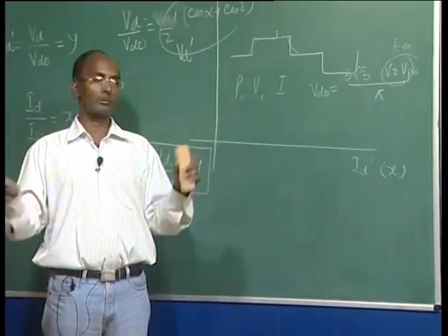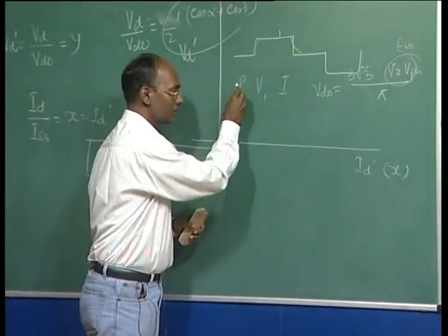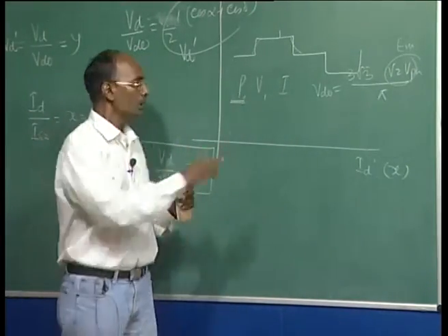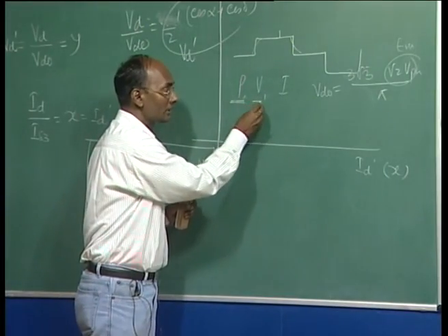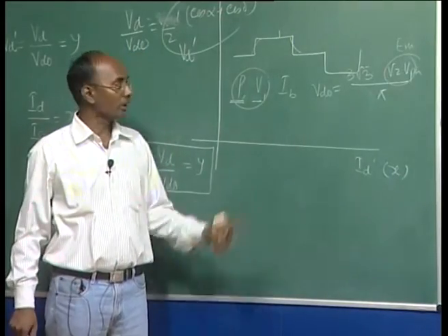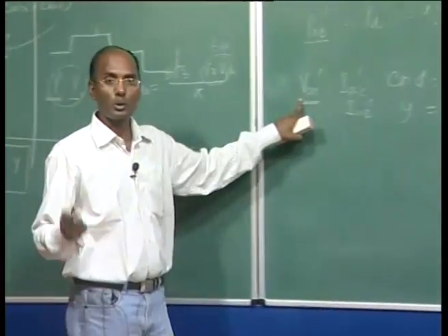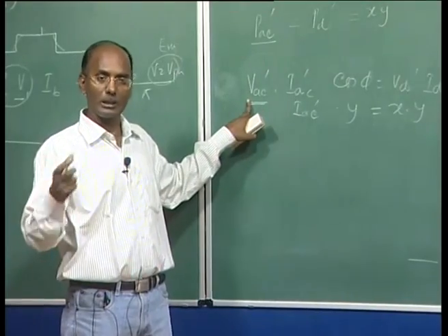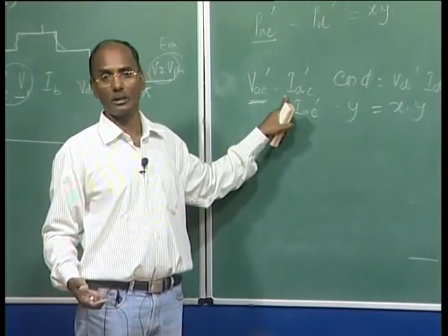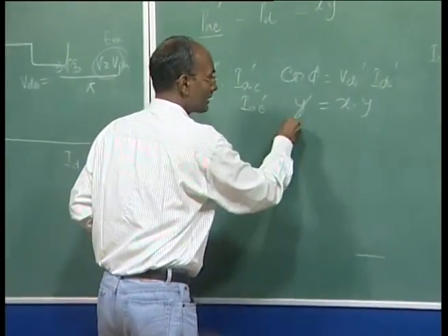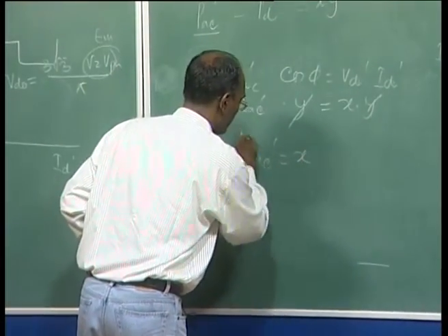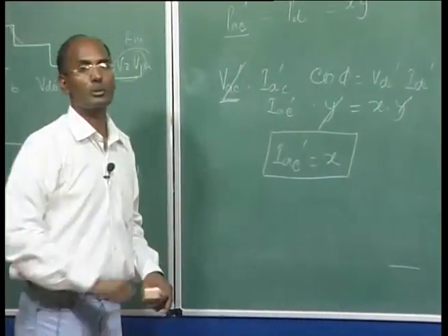So in any per unit system, normally this power is basically apparent power, and in the whole transmission system the active power and the MVA are almost the same. So this power and this voltage base value are defined, and the I base is calculated. In this case, the voltage base here is unity, because you divide the actual value by the same base value, so this becomes unity. So this cancels, and your IAC in per unit will be your X. So it is easier to define.